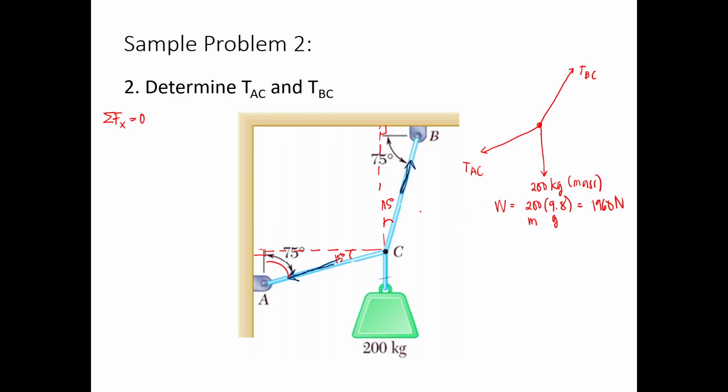All right. So summation of forces x equals 0. So tension AB, 75 degrees. So that will be sine function, right? So if you try to draw the system components, this one is the horizontal aspect. This one is the vertical aspect. This one is the horizontal aspect going to the left since it's tension, then going downwards.